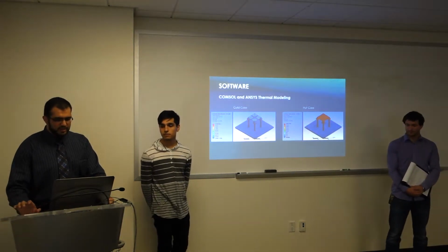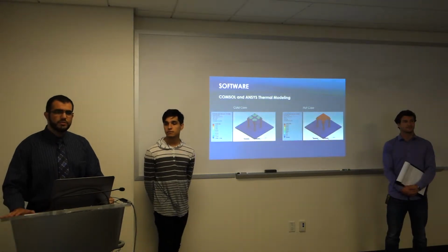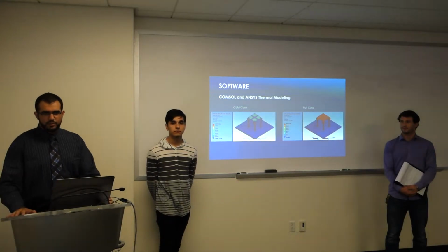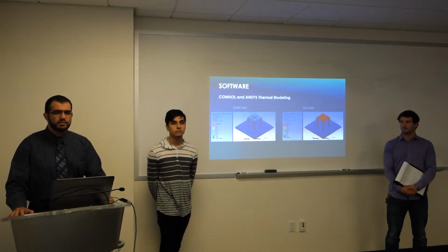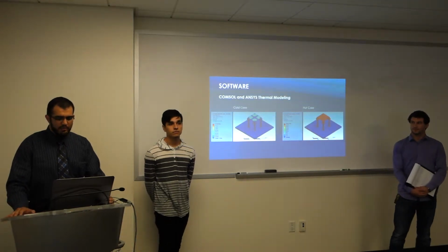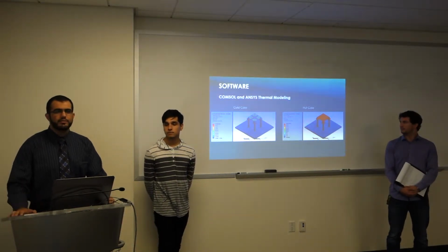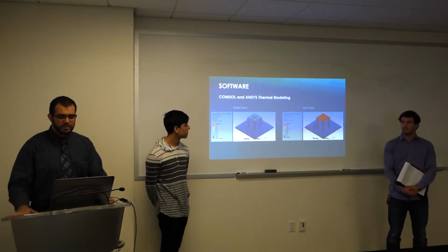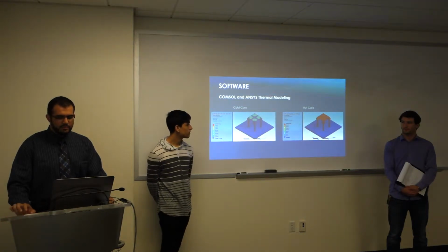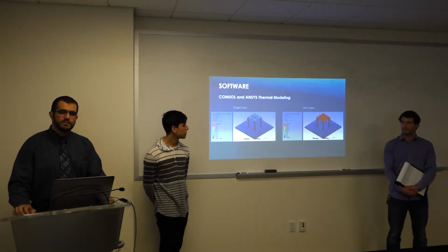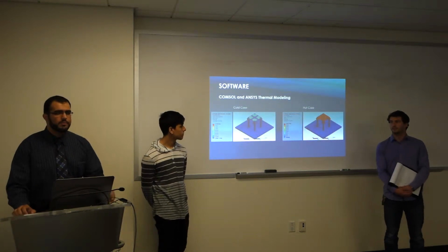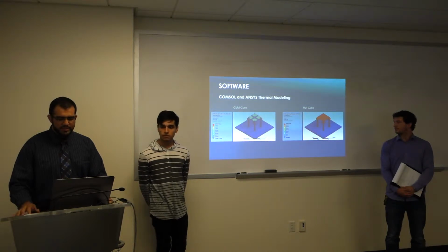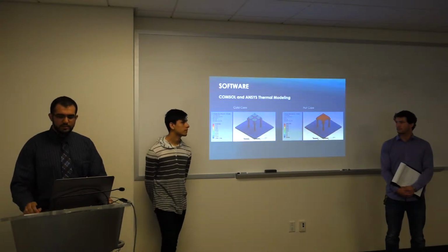So for software-wise, we first started out with COMSOL, and we tried to model our radiator in COMSOL since the beginning of this year, in the fall. However, we came across some difficulties in trying to get a solution to converge. We've been going back and forth, trying to figure out why our model is failing to solve the simulation. In that case, I took the route of using the ANSYS software to see if that could help us get a solution. I was able to model it from scratch, and thankfully it worked right on the spot.